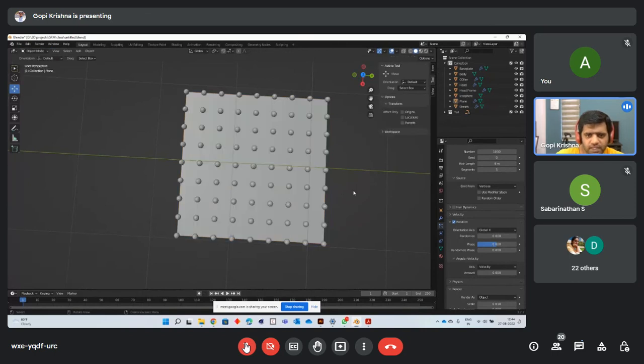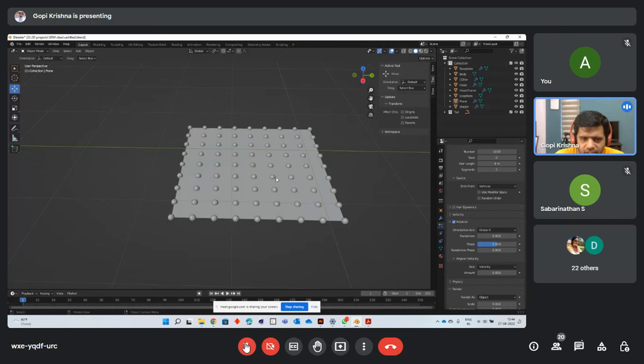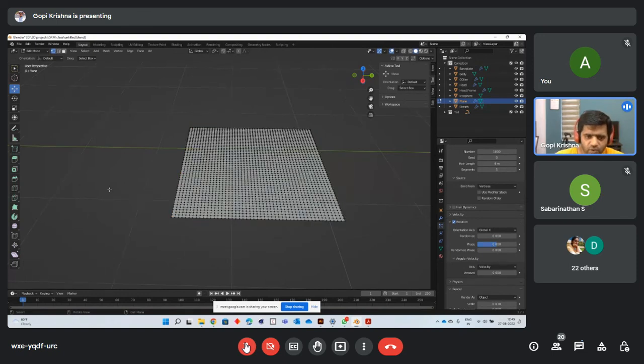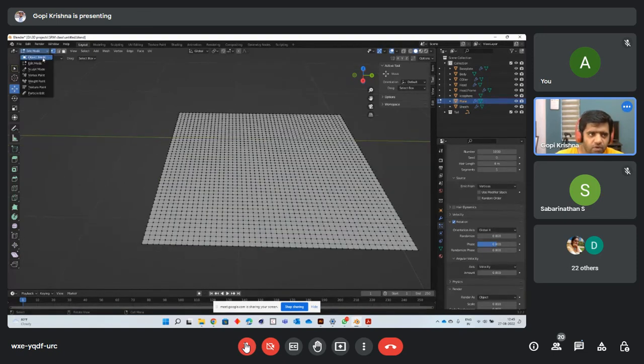Now you go back to object mode, see. Now it has placed one circle on each of the vertices. Now it becomes a little more ordered. So just like that, you can add as many vertices as you need. It will give an even distribution of these things. For example, you go and subdivide and make it 5, with very small subdivisions like this. Go back to object mode.